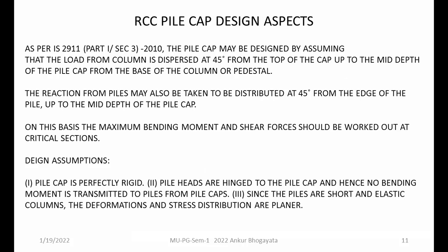But here, as per the IS 2911 code, there is a code which is dedicated for pile foundation, basically not for the pile cap design, but somewhere and somehow they have shared some details regarding pile cap also. Like it is desired that you assume that the forces are transferred at 45-degree from the top of the cap up to the mid depth of the pile cap from the base of the column or pedestal.